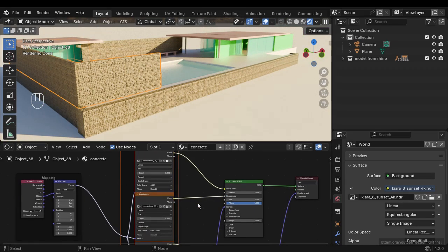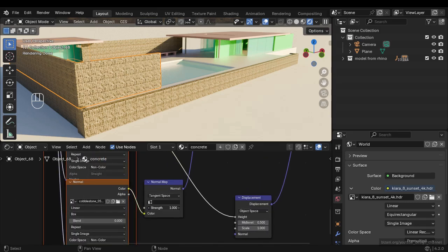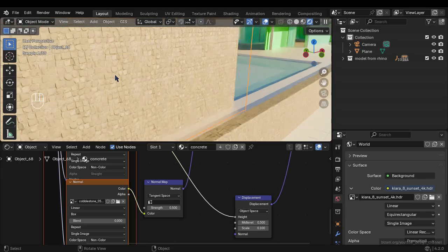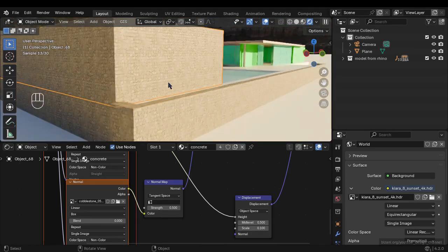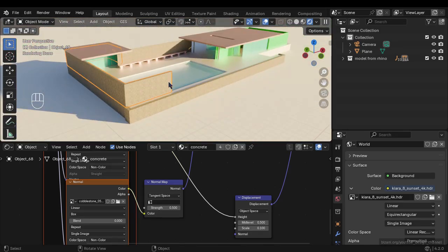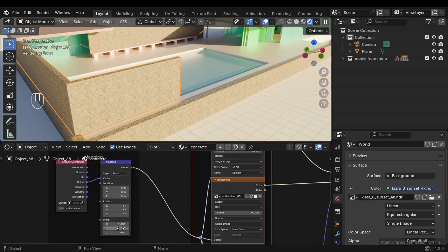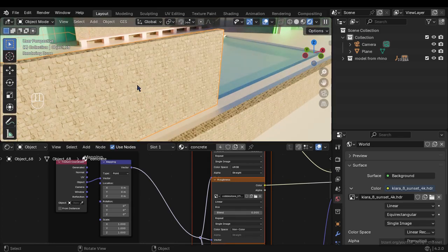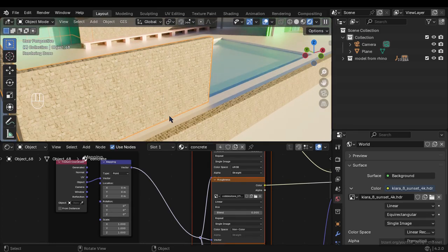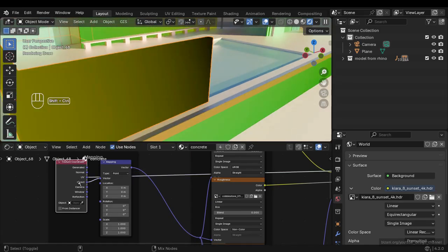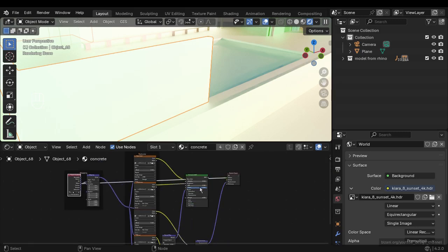And then if we decrease the normal a bit to 0.5, and also the displacement, because the values are too high now, maybe way less, we can see what we have here, the PBR material. As you can notice, there is an obvious tiling of the PBR, and because we are in object and the scale is 1, you can see that this is 1 meter by 1 meter for each one. If I click Control Shift on the object, we can preview what the object is doing here.